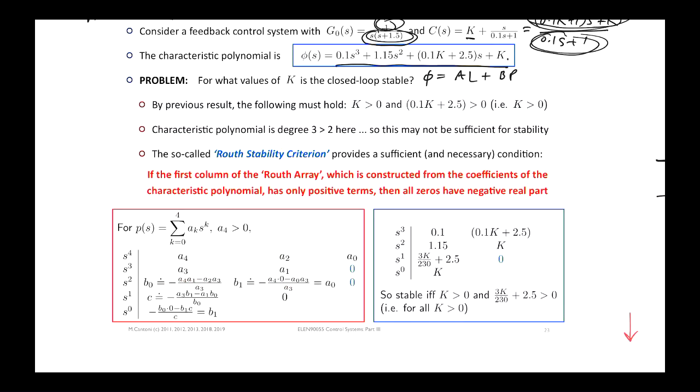And on the top, we've got the determinant of a matrix whose first column is the first column of the 2 rows above, and the second column is the column 1 position to the right from the 2 rows above. So it's A4 times 0 minus A0 times A3. Which turns out to be equal to A0.